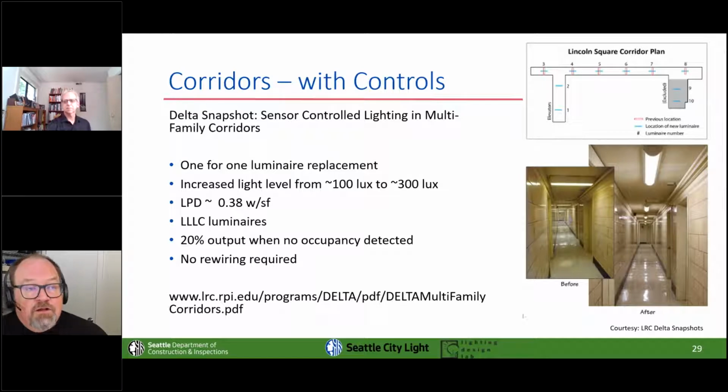Now, they added luminaire level lighting controls. So as Duane mentioned earlier, basically what this means is that you have the light fixture and all of the dimming components and sensors right in the light fixture itself.